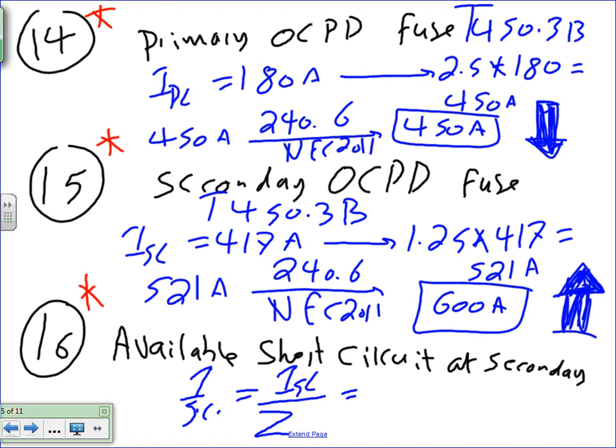Dustin, the code allows me to go 600 amp. Can I put 500 amp? Anybody can answer. If the code allows you to go 600 amp, can you put less amps than the code allows you to? Yes. So what's the restriction in amps? The restriction in amps is you can't go higher fuse-wise and circuit breaker-wise, but you can go lower. One more here. If I am restricted to 450, can I go 400? Yup.